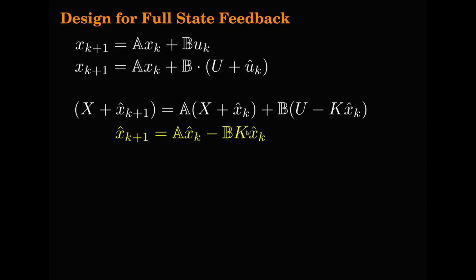So this will be the small signal equation. So remember this, x(k+1) hat can be written as (A minus BK) x(k) hat. So this is one equation that we can mark as equation number 1. We need that to derive the design equation for Nx, Nu and K.